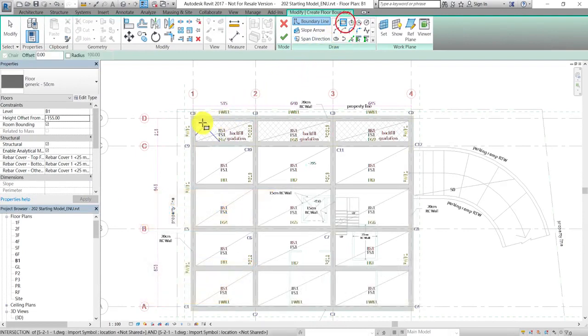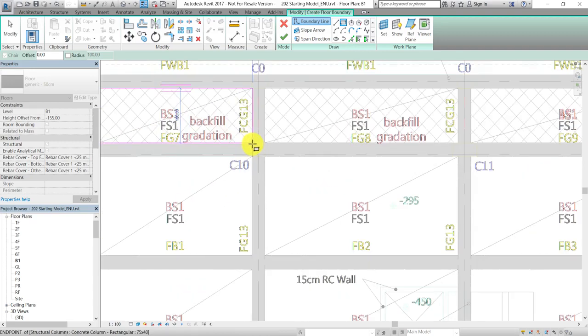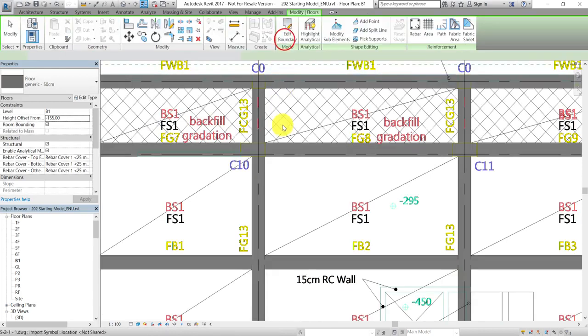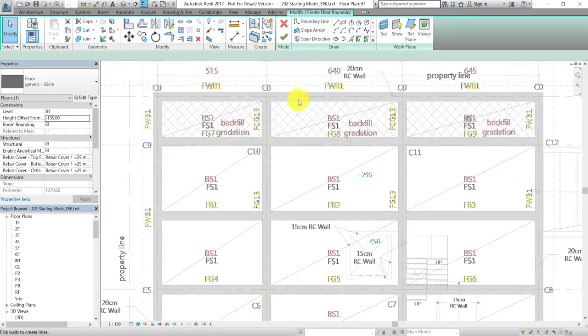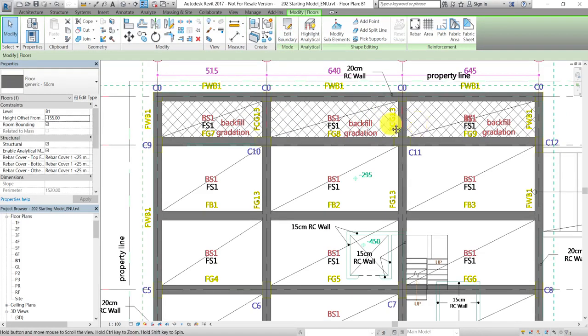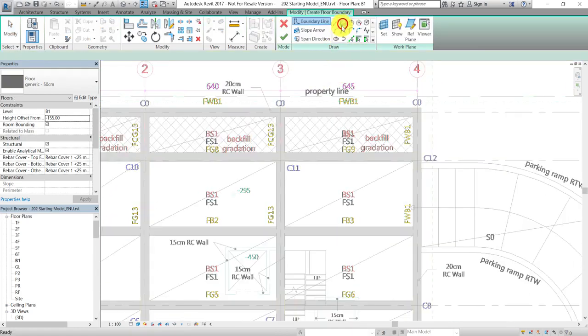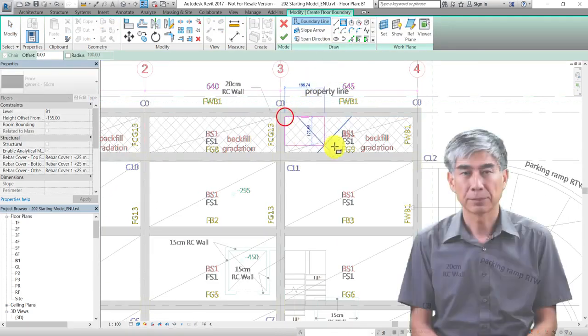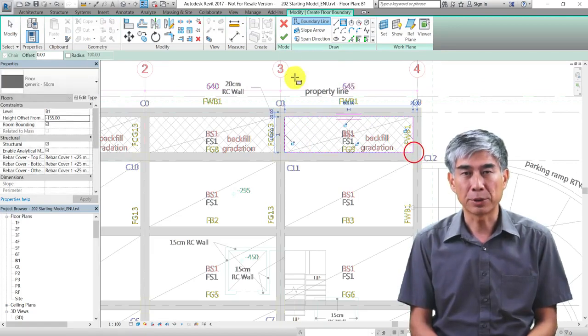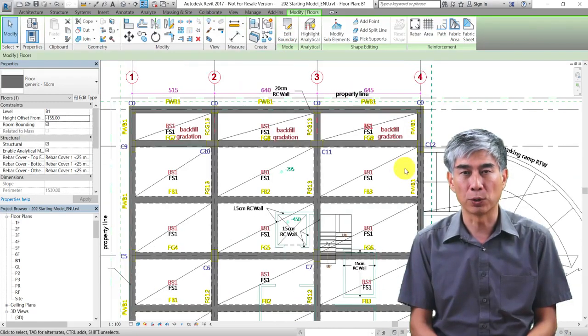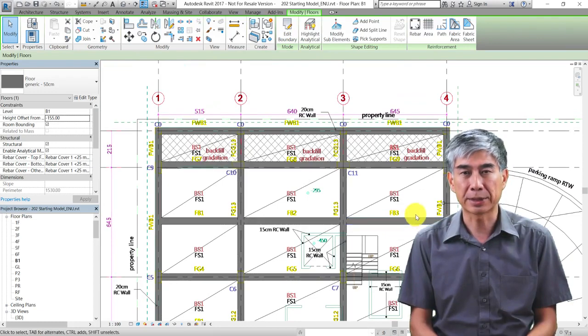Now, go to the drawing area. Set up the foundation floor according to the closed area formed by the beams and foundation columns. Draw each floor separately in the sequence of left to right and top to bottom. Here, we only demonstrate how to set up the top 3 floors. You can repeat the same steps to get the rest done.